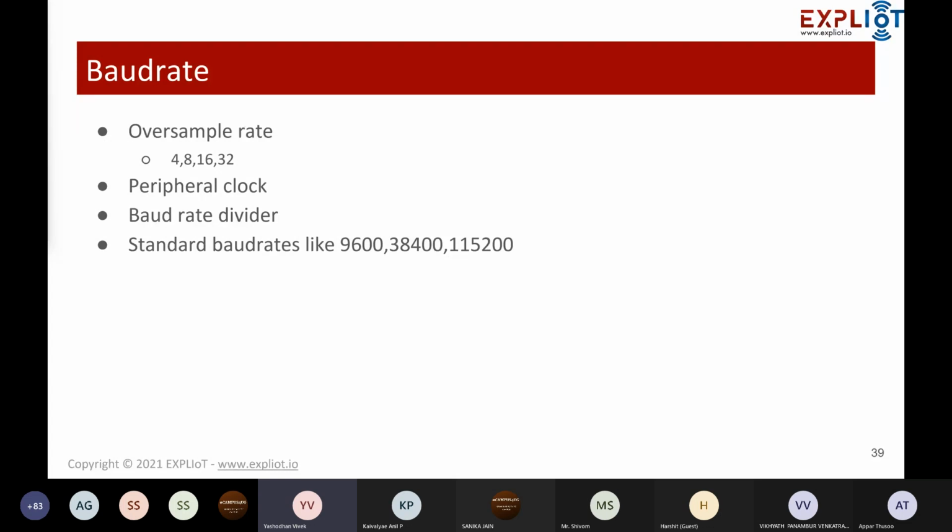Now, this advanced high-speed bus is basically driven by the complete clock and your PLL system, and eventually the peripherals derive the clock from that. When you have a UART communication, though it does not have any clock for reference, to run the particular system we need a clock. And this particular baud rate, such as 9600 bauds per second, is basically generated from a reference clock. So whatever clock your peripheral is using, from that you generate particular baud rates with some formulas given in the data sheet, right?